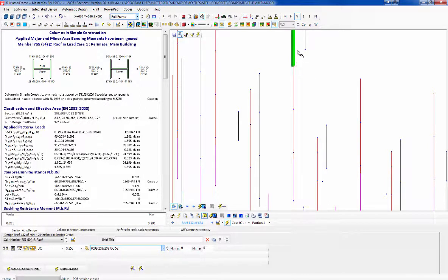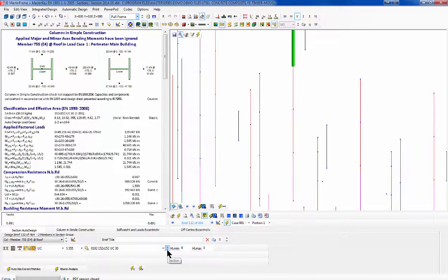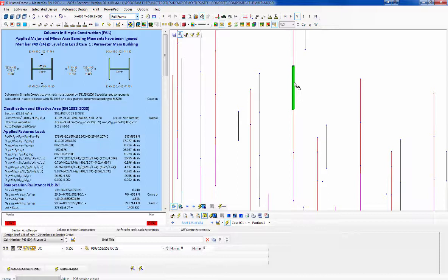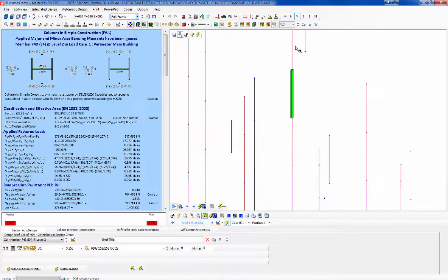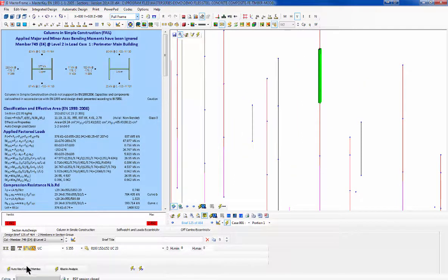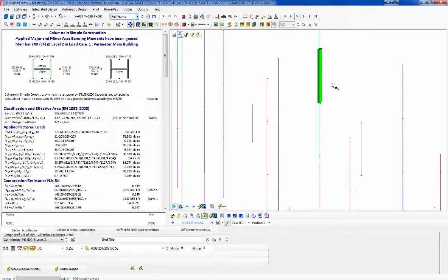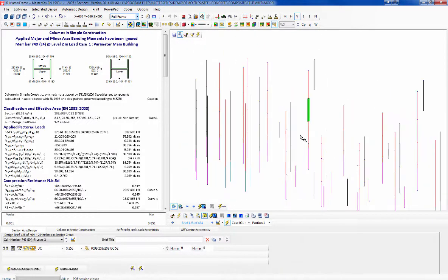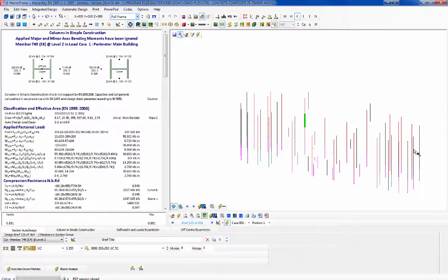So if I sized up this section and I just did that manually, I could come all the way down to 23 and it would work. But if I came here, it now doesn't work because those two members were tied together. It's, again, using this trick, we're able to say these two members are the same size. So it now sizes it up so that both of these lifts have the same section size. And that's been applied all over here.